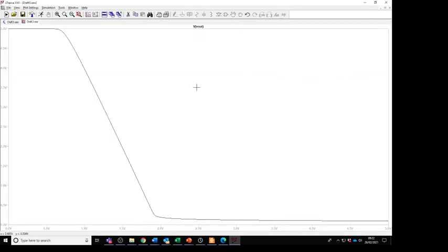And so this is replicating the transfer function that we got when we analysed the common emitter amplifier. So you can see that for small voltages going in, 0 volts going in, we get 5 volts out, and that's because there was no current flowing through, the transistor's off. As we then increase the voltage, we get to the point where it does this transition, which we noted was exponential, and then gets to the point where it's effectively saturated and can't go any further, which is close to 0 but not exactly 0, and then we don't get any more life out of it at all.